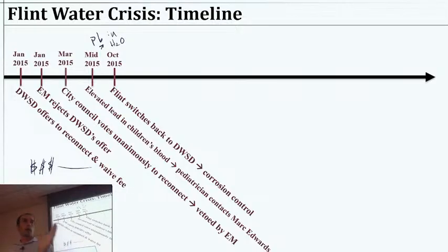Because as soon as we've got corrosion-controlled water, we are no longer etching away at our pipes, and we are allowing mineral deposition on the pipes, stabilizing it. There might be a few particles kicked off from all the damage that was done, all the corrosion, but even with lead pipes in the systems remaining, the problem goes away very quickly once we adjust the chemistry properly. So that is, in a sense, the end of the Flint lead crisis.